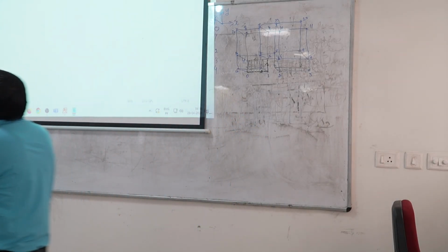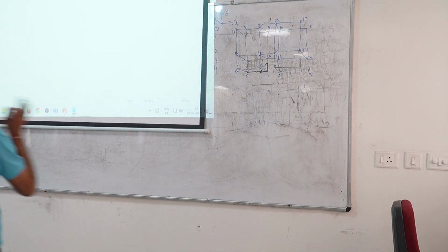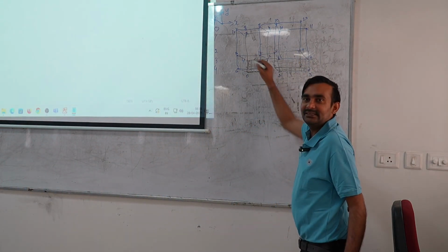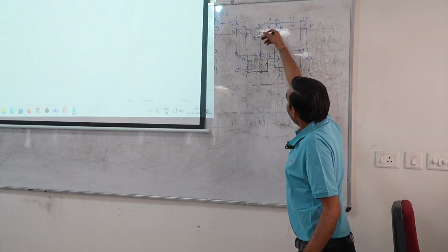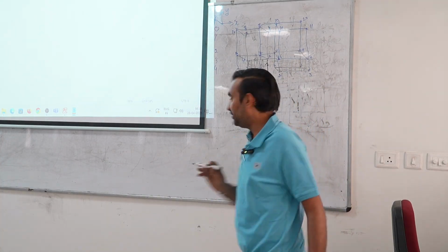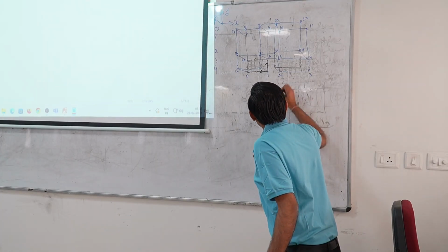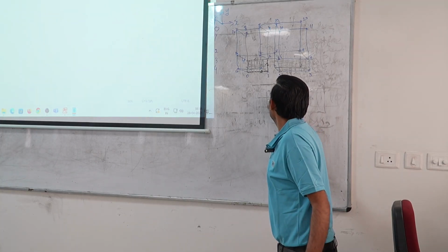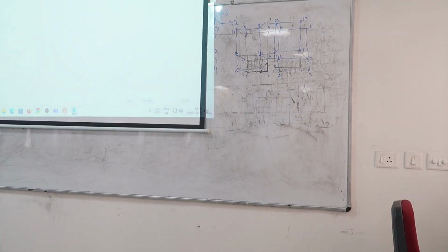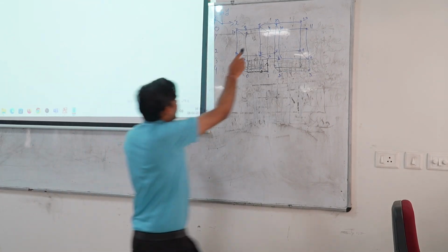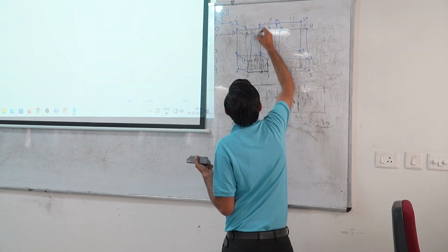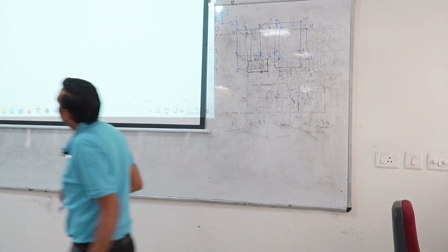The next one is 23 42 1. Now you have to keep one thing in mind. If in this box I have used 23, then in the next box also I need to use 23, because whenever fluxes transfer from one cell to another, the connections should be pointwise, then only correct fluxes will be transferred. So in the x direction for this cell, I need to specify 23 only. If I specify 23, then all these points will be connected. And then I am having 42.